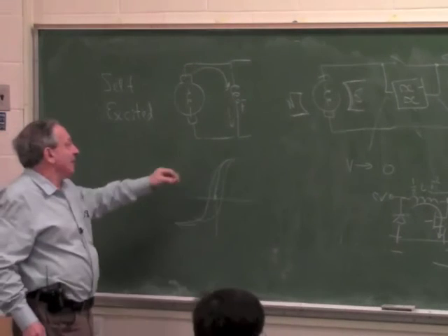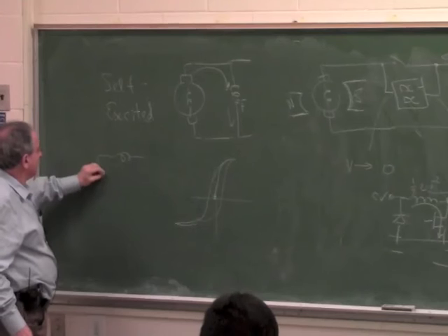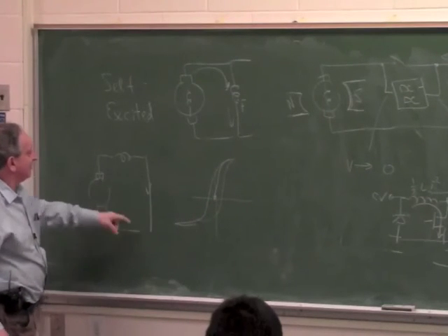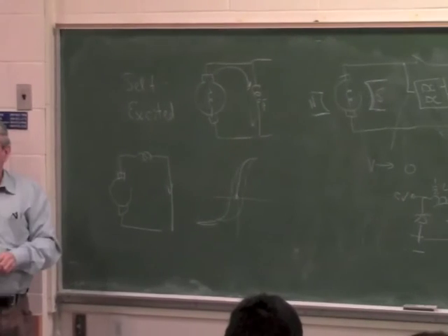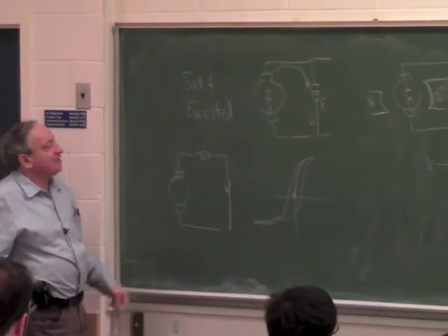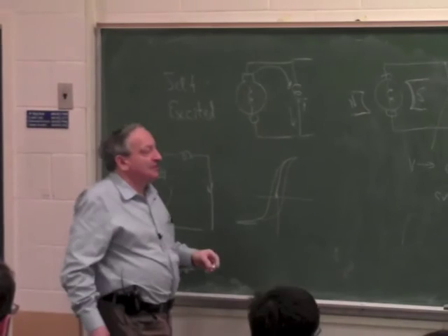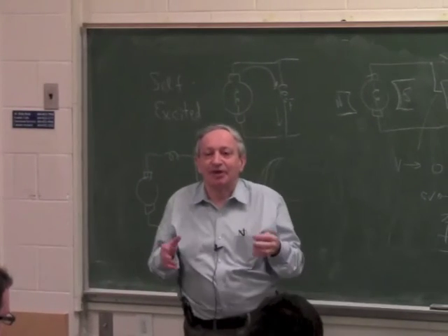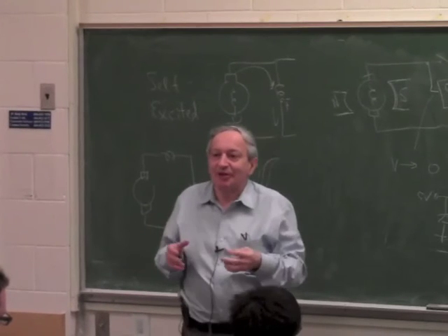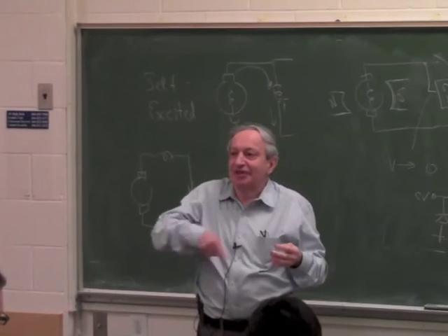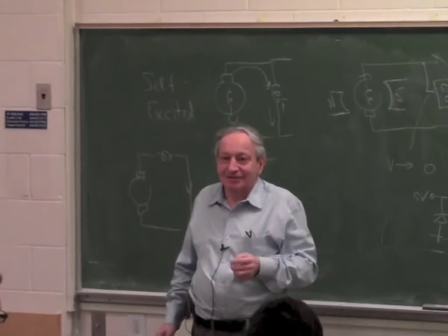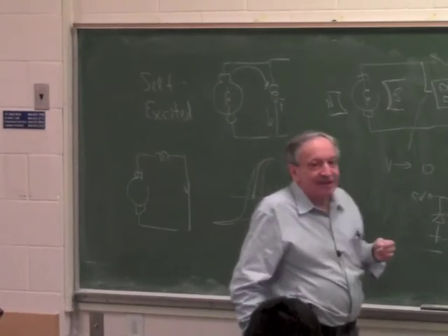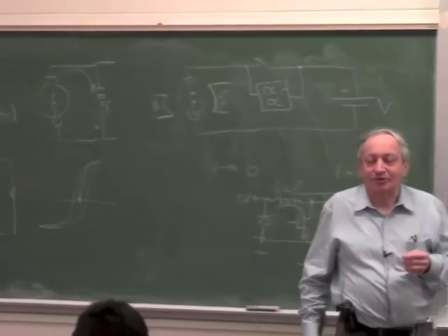Especially for parallel wound. It's also true for series wound, but in series wound you have to close the path here so current can flow. So basically, in all DC motors, it's easy to understand how dynamic braking is done, because a motor becomes a generator if you just turn it. It takes a little bit more thinking: how does it work in synchronous motors?